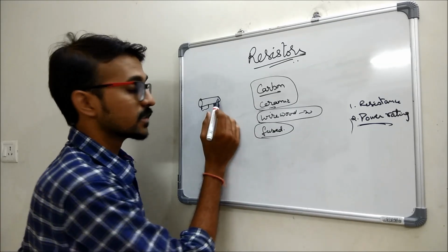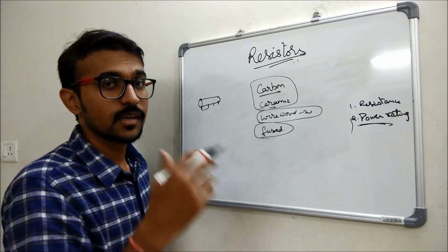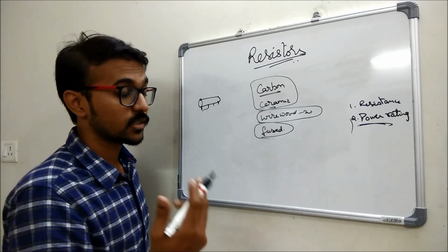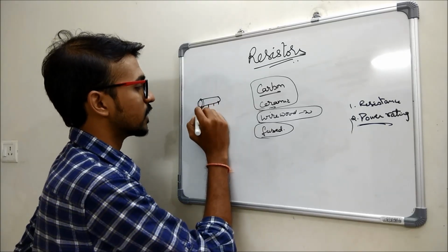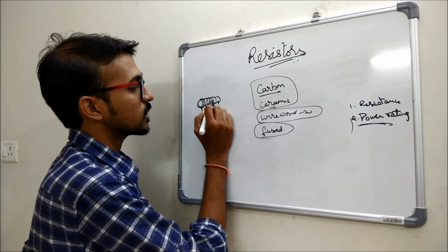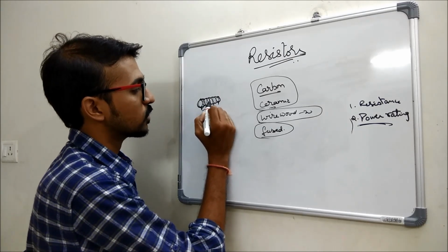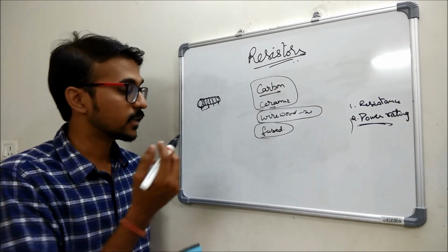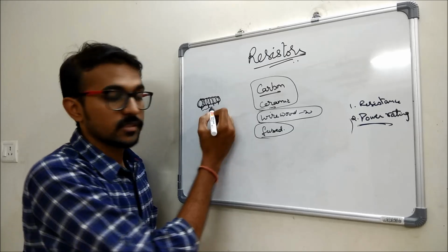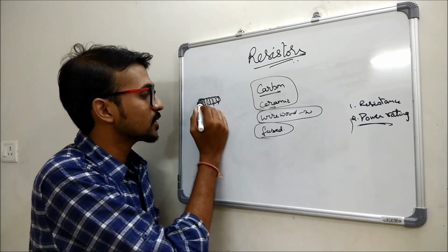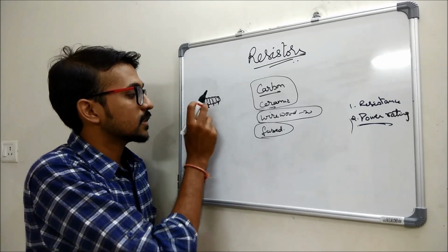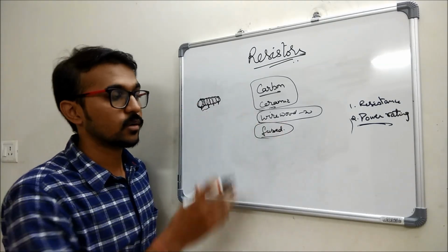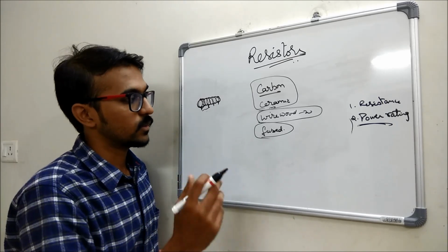And if it's higher resistance, then the fan will turn slower, and if it's lower resistance, the fan will turn faster. What this consists of is a thin wire wound around this ceramic, and at different points of this wire a connection is taken. So the resistance of this wire is taken there, and this resistance is used in a circuit or a regulator or whatever is there.